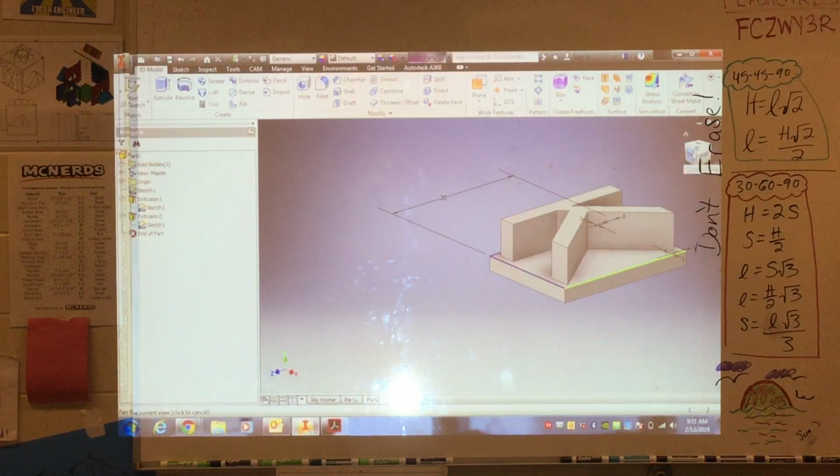Now, because I'm doing a mold, I need to do one extra thing. I'm going to make what we call a draft. And a draft is nothing more than a fancy word for I'm going to take the sides of my letter and I'm going to angle them in. And the reason why I want to angle them in is that when I make my mold, if I had them straight, every time I pull that letter out of that mold, it's going to drag on that edge. And there's a bigger chance of me breaking something or ripping something or it being too hard to pull out. If I have them sloped in, then as soon as I pull on it, notice as it's getting wider as I pull it out, I'm no longer touching the side, so it's easier to pop out. That's the whole purpose of a draft.